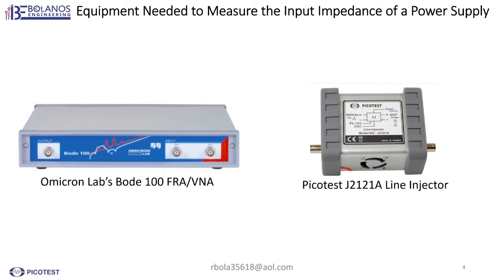Here you have the Bode 100 on the left. It's a frequency response analyzer, and it is also a vector network analyzer. These are the two pieces of equipment that you need to measure the input impedance. On the right, you also need a line injector, and the line injector that I'm using is the Picotest J2121A line injector. Using these two will allow you to measure the input impedance.